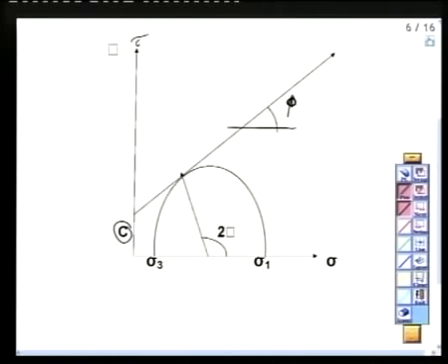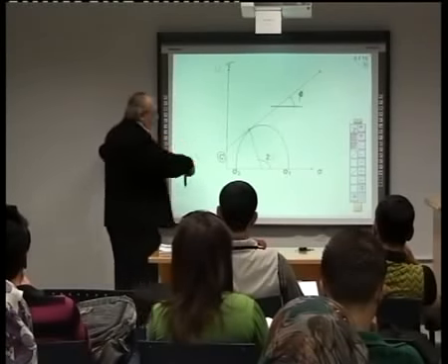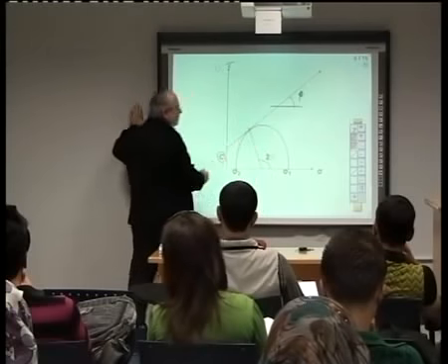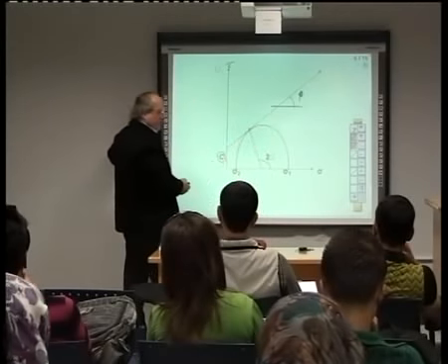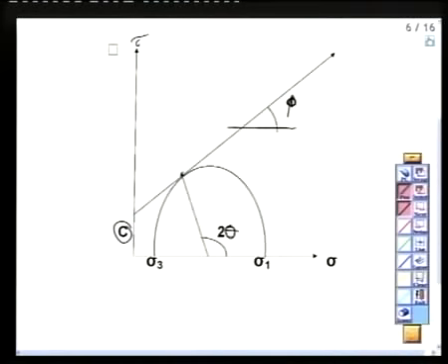Now, if we took the sigma 1 and sigma 3, of course sigma 1 is greater than sigma 3, remember, and we draw a circle. This circle is tangent to this line. Then failure will take place at angle 2 theta. Remember, when we found the Mohr circle, we said that the origin method, we used 2 theta.